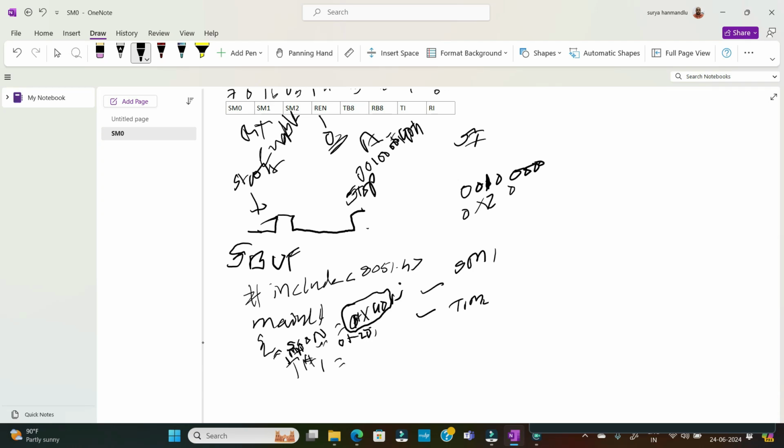But timer 1 high only will set the baud rate. Let me select a default baud rate. For which value you will get how much baud rate, I will tell you in another video, otherwise this video will become lengthy. The next and last step is we have to start the timer.